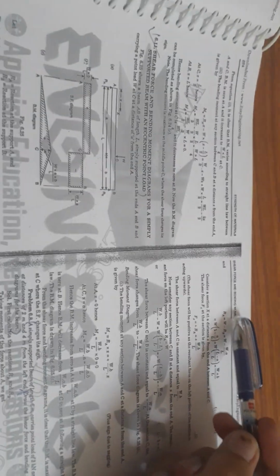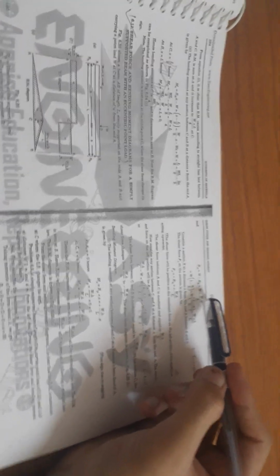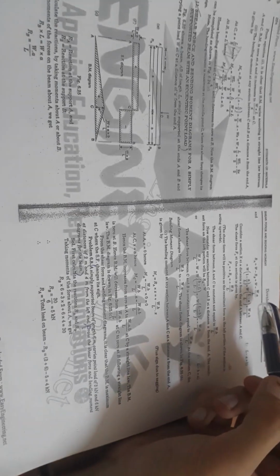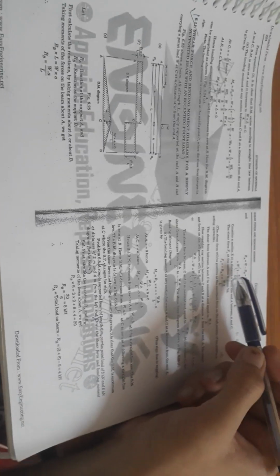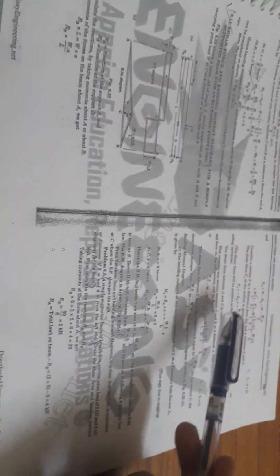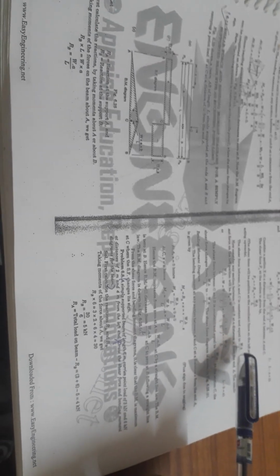RA is equal to W minus RB, which is equal to W minus W into A by L, which is equal to W into 1 minus A by L, which is equal to W into L minus A by L, which is equal to W into B by L. Fx is equal to plus Ra, which is equal to W into B by L. Now considering any section between C and B at a distance x from the end A, this is the diagram.